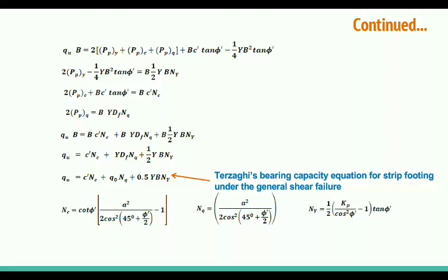So this Nc, Nq, and N gamma are constants, called Terzaghi bearing capacity constants, and these constants like Nc depend upon the cohesion of a soil. Okay, that belongs to the cohesion, right? Nq depends upon the surcharge. N gamma depends on the weight. There is also phi.